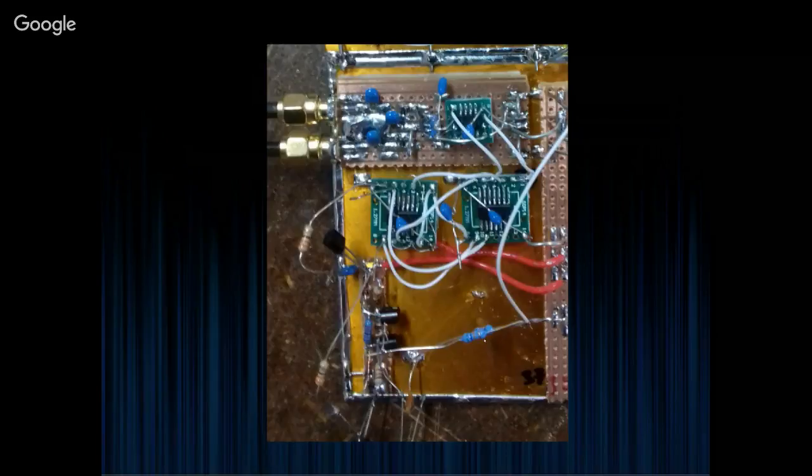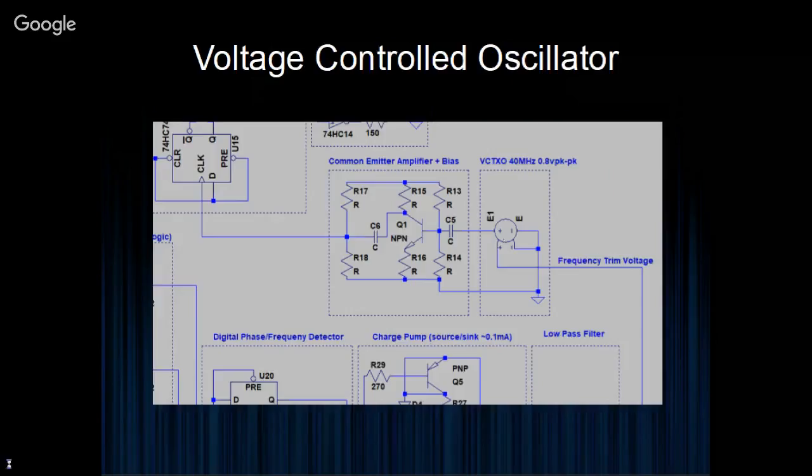And then these funny little resistors coming out here are just to ensure that I don't exceed the voltage control specification on the oscillator. Where those two resistors stick out and join the white wire is now our control voltage for driving the trim on the crystal oscillator. Coming up the bottom right-hand corner is the frequency trim voltage, and that is a simplified representation of the voltage-controlled temperature compensated crystal oscillator. So I got that acronym wrong as well.